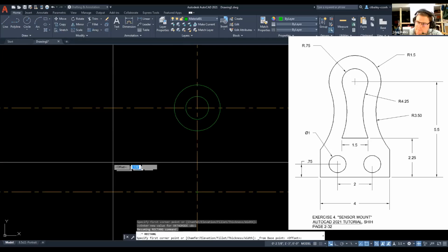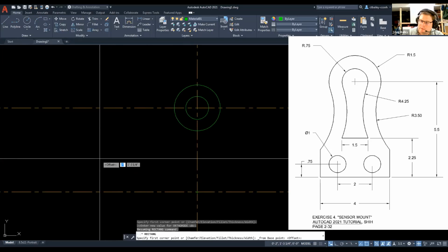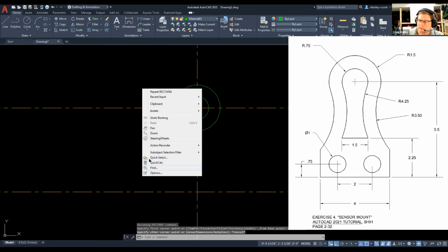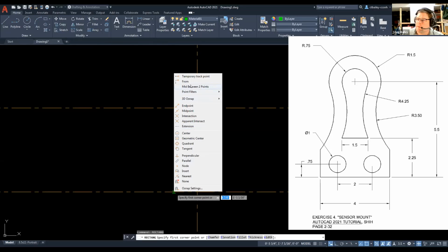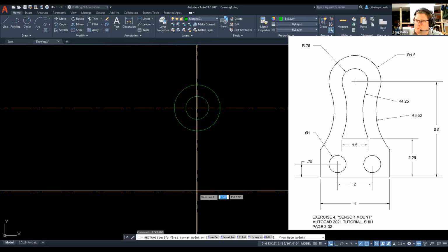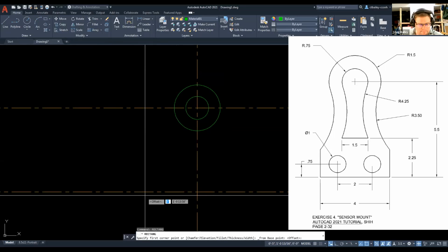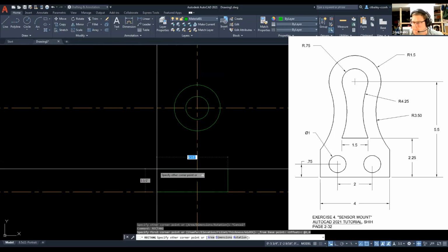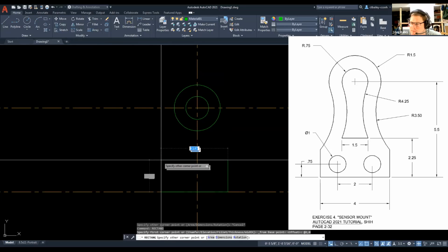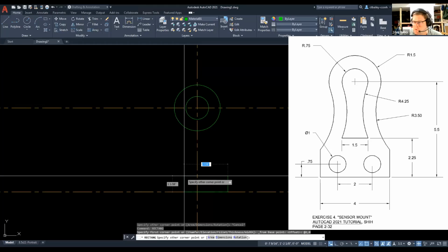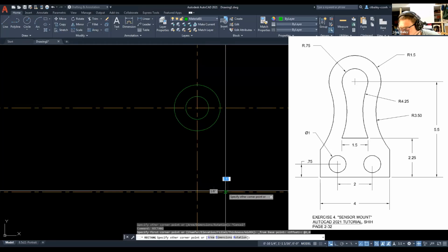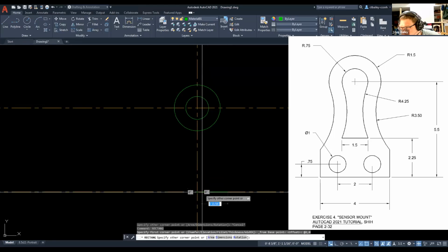offset, and I'm going to send my cursor this way, and I think this will work, to, it didn't work. Let me try it again. It didn't work. I'm going to have to do the @ symbol. I do want the @ symbol. At 2 tab 0. Enter. And that's exactly what we wanted to do. So the rectangle command is starting at 2, +2 from my pick point, and 0 up.